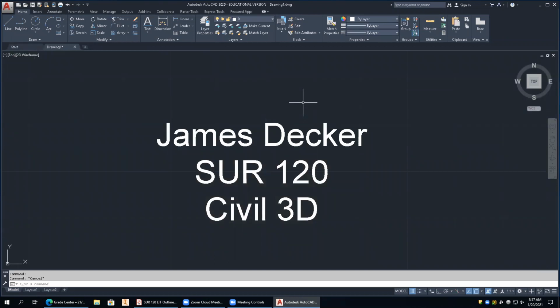So we can go ahead and create as many styles as we want. Or we can use just straight fonts. But if you're using this type of text, it is always driven by a style. So this text will be driven by that style. Okay? So we're going to take a look at the style command now, because you need to know how to edit styles and or create them. Because we don't always want to use that one.